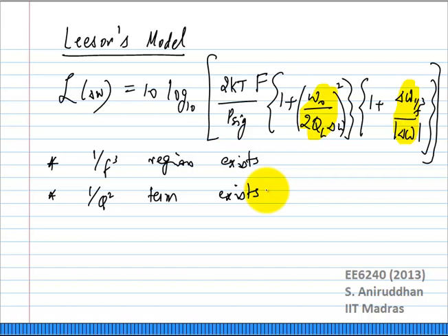However, we also know that when we say Q here, we don't necessarily mean just the Q of the tank or just the linear Q. We are also talking about the fact that this Q itself is a function of frequency, not just a function of frequency, but a function of delta omega. But definitely this Q behavior with delta omega is a strong function of the initial Q you start off with, because to compensate for the losses due to that Q, you try to build an active resonator. So they will be strongly correlated.